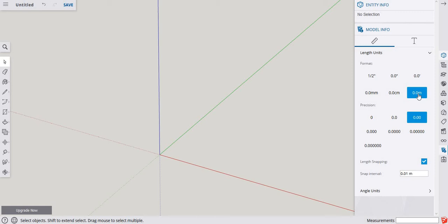Now the reason why I do that is because when you're making small precision parts to be 3D printed, like threads, and they're all in millimeters, and it says 0.25 millimeters, and you're trying to do intersecting faces and everything, those faces can glitch out and leave open holes in the mesh. So if you scale it 1,000 times, so it's 0.25 meters for a face, it's easier for faces to stay closed rather than lose any geometry. So model big, and then I'll show you how to scale down with the tape measure tool. Let's discuss that now so that you don't panic.